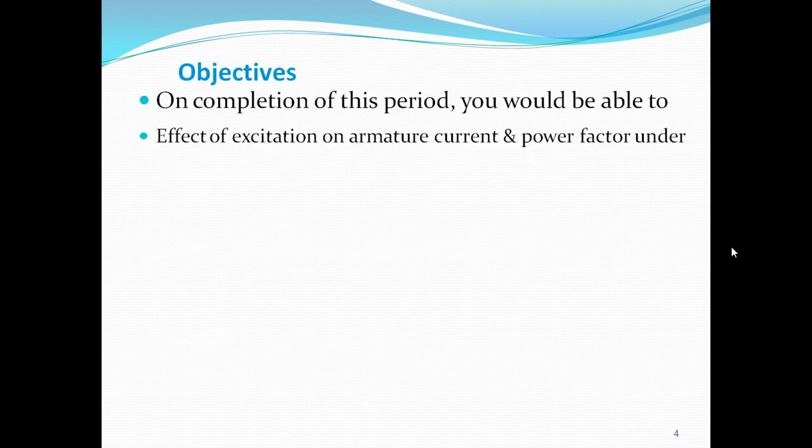So today we will see the effect of excitation on armature current and power factor under normal excitation, under excitation, and over excitation.